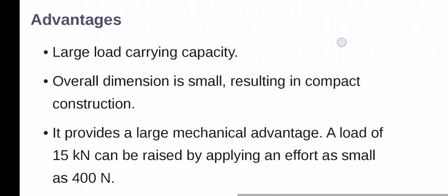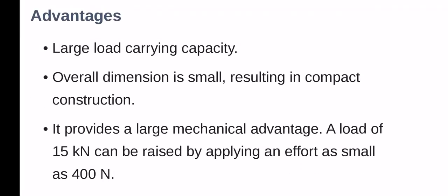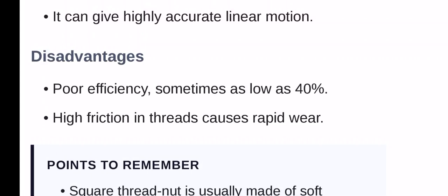Advantages: large load carrying capacity, and the overall dimension is small, resulting in compact construction. It provides a large mechanical advantage. A load of 15 kilonewtons can be raised by applying an effort as small as 400 newtons. It can give highly accurate linear motion.